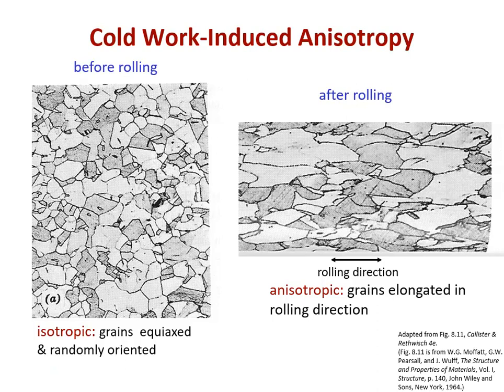And we're going to see a selective elongation of the favorably oriented grains with each increment of deformation, or increment of shear stress. And so you can see on the right-hand side, several of those grains are not equiaxed. They're now elongated, mostly left to right. But there's a few in there that are still more or less equiaxed. And those are the ones that were not originally oriented to take good advantage of the directions of applied shear stress. Eventually, with additional applied stress or additional required strain, those will deform as well, but they will